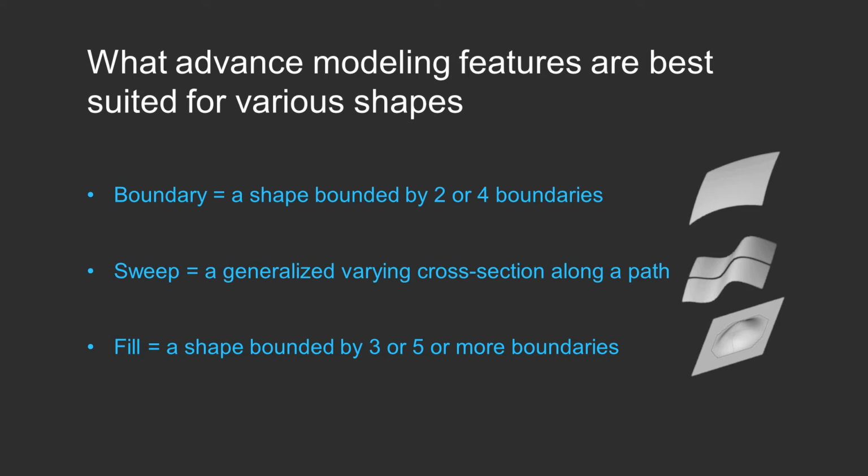And it works very well because, if you were to create a fill or a boundary, you may want to derive tangency at the edges that you're filling. Fill has a unique algorithm in that it has a generalized tangency or curve continuous matching that doesn't rely on those boundaries.